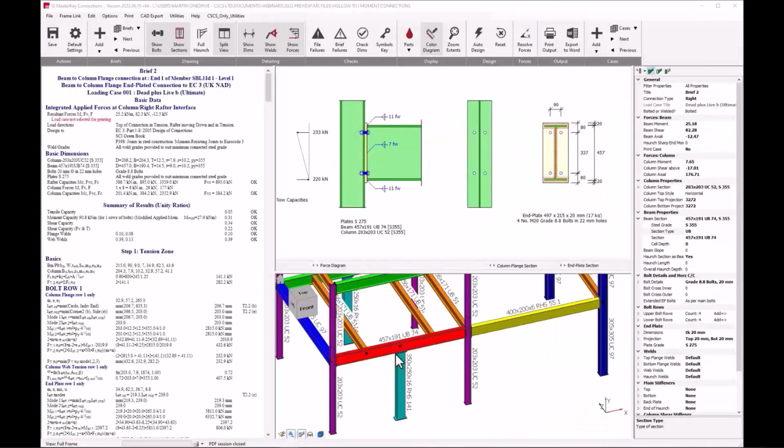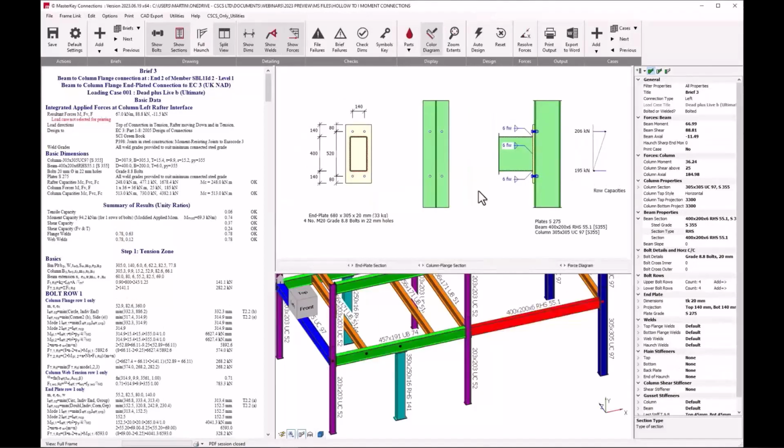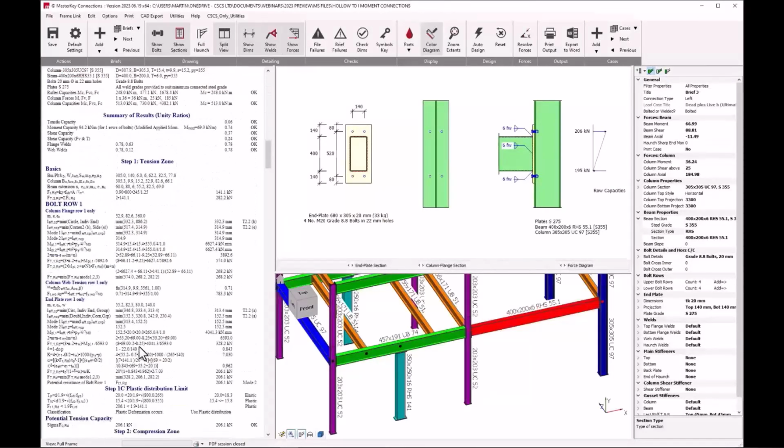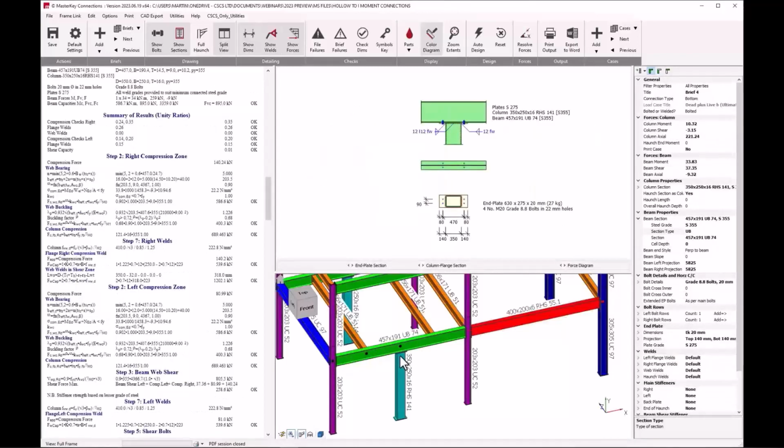So onto our little demo, a very simple frame which demonstrates all of these nice new features. Just to show you, this is our eaves beam to column moment connection where both elements are an I section, whereas on the other side we have a beam that's a hollow section connecting to an I section column, and you can see then the connection that's being produced in that scenario. The approach used is extended end plates with bolts in the extended end plates. Now the CIDECT rules with regards to the end plate bending for mode 2 and complete end plate yielding are all taken into account, which are slightly different from the normal end plate bending rules.